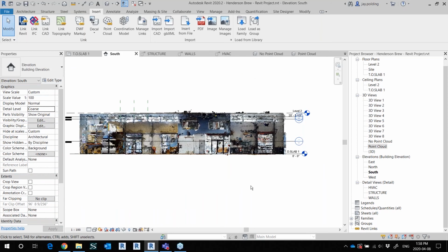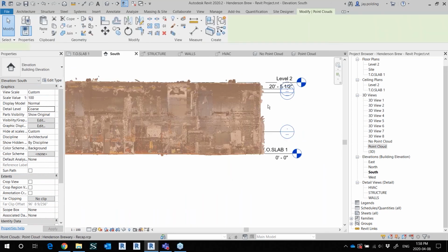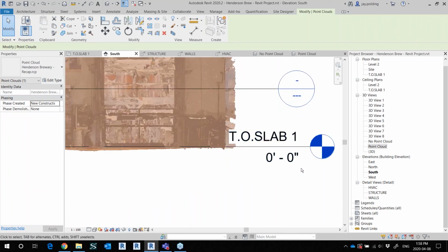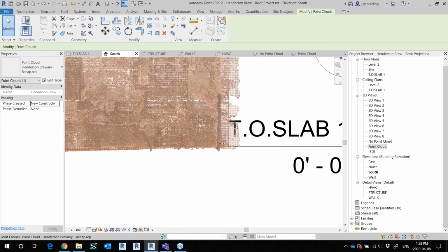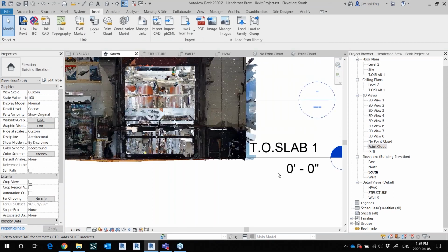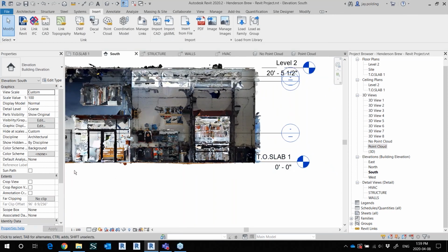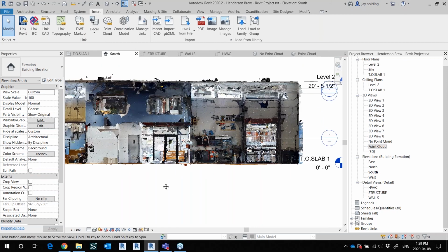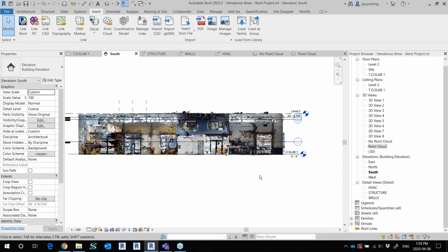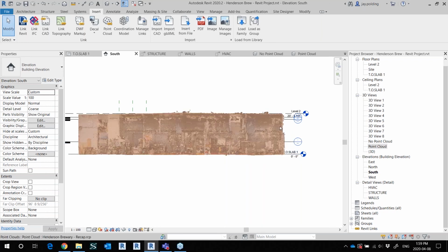And what I usually do right away is I'll go to an elevation view. Looks like that. And what you want to do is just take the point cloud and move it down to what would be considered 0. So you just move it down to maybe the top of concrete slab at the floor level, and you can put that there. Of course, slabs do deviate in their elevation a little bit. That's the way they're poured usually on purpose, especially in a brewery. So you're going to get a little bit of up and down here, but basically that's in the right place. And the more care you put in that, the more accurate you will be. Okay, so it's moved down.